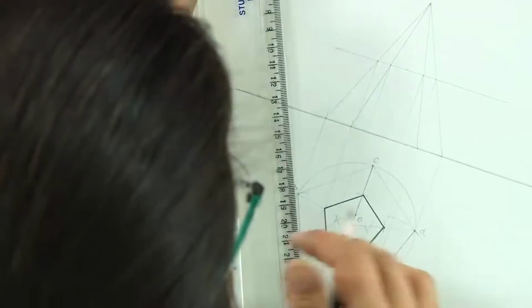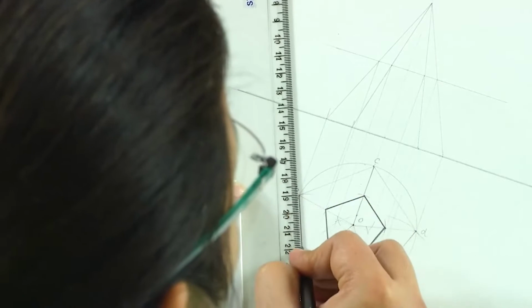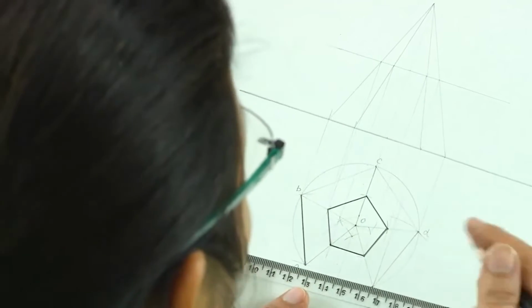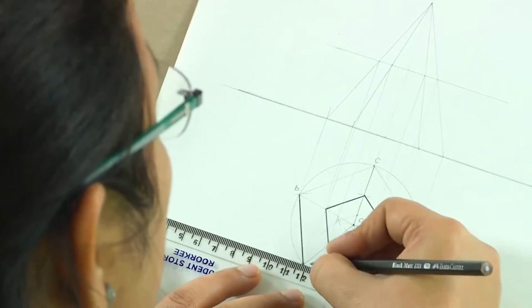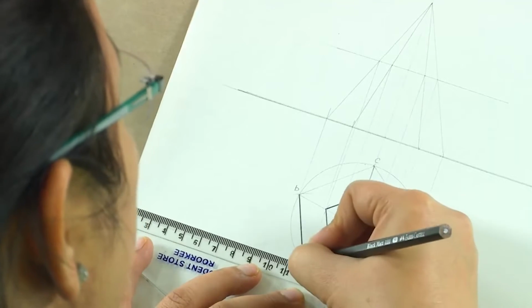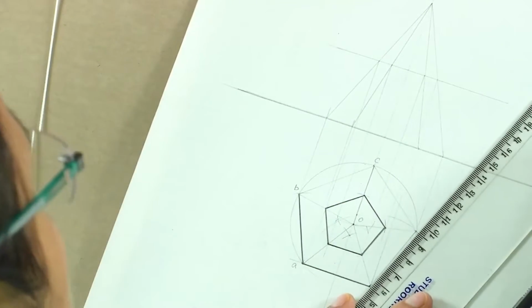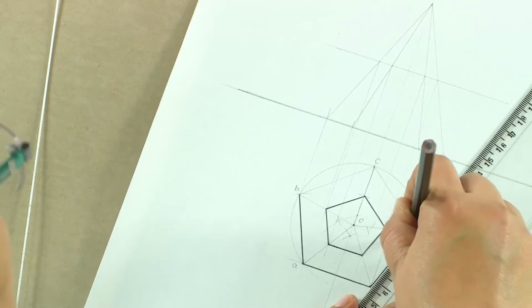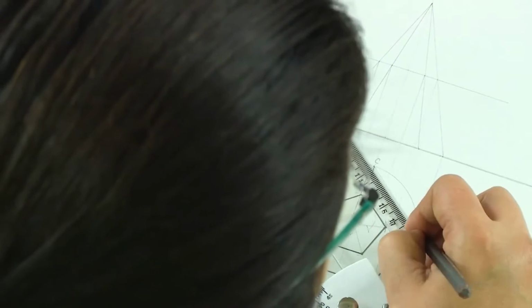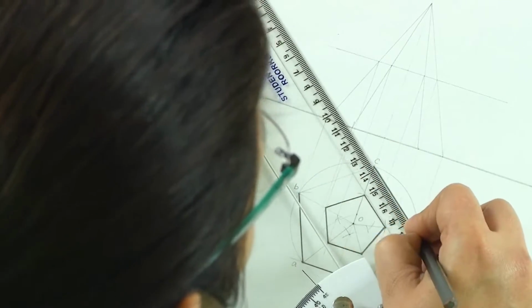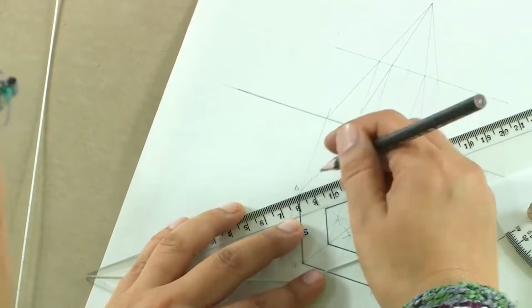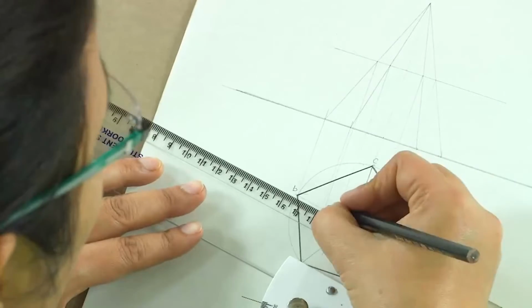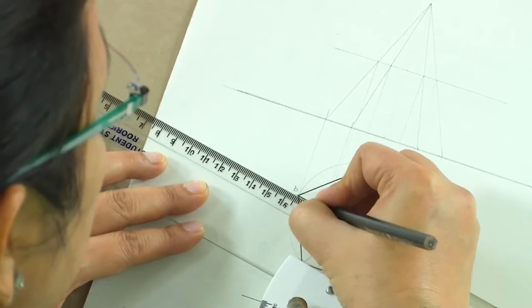So, what do we see here? When the section plane is parallel to the base, the shape of the section is similar to that of the base. It is just that what will be seen in section will be slightly diminished. This is the final top view which you will see, and we will also have these edges because these edges are still intact.